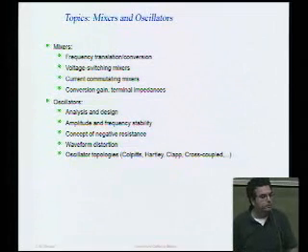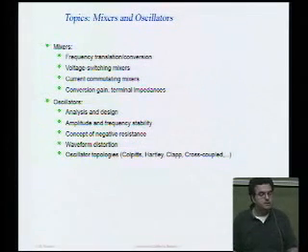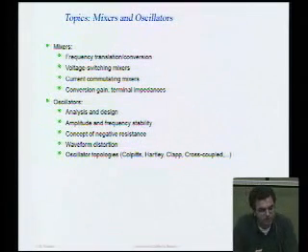The next few topics hopefully are going to be really interesting to you guys because they're going to be new. We're going to talk about mixers and oscillators. As we discussed, mixers are circuits that perform frequency translation. They're either nonlinear circuits or time-varying circuits, so we're going to have to learn to analyze them. Turns out that SPICE, actually standard SPICE, is not a very good tool for analyzing mixers. It's very slow. There are better tools for analyzing mixers, namely harmonic balance simulators and periodic steady-state simulators, such as Cadence Spectre RF. And that's when we're going to learn about these simulation tools.